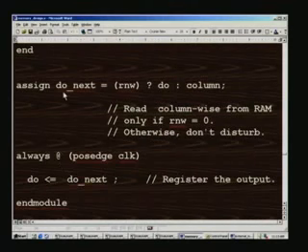Once again here we need to output this. We are talking of the submodule RAM_RC, and the corresponding output is still a combinational output only, that is assigned from this column. This column we have seen earlier, we are reading column wise. How to read we have already seen. What we have read and put in the column earlier, now we are going to output here to DO next, provided R and W is low. So low corresponds to this one. If it is write mode, naturally DO will be taken as DO next.